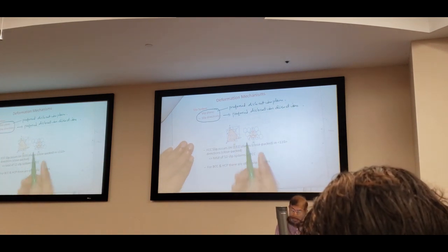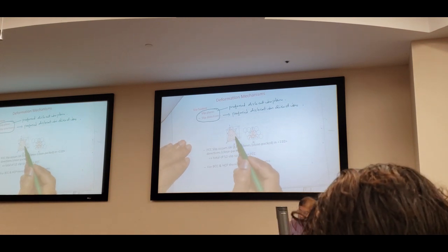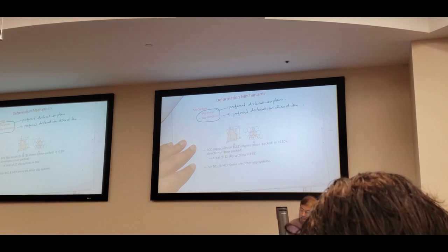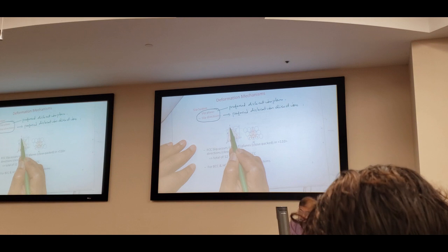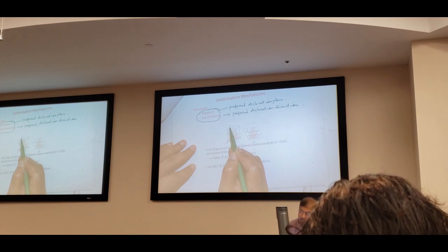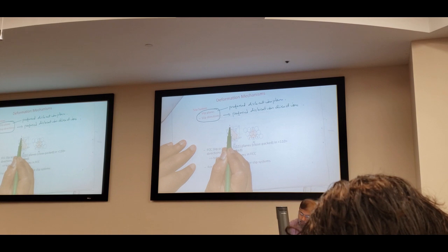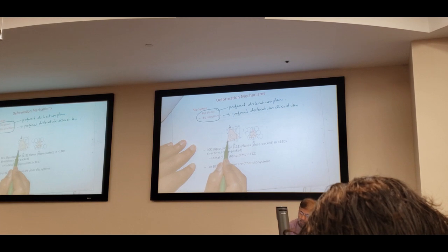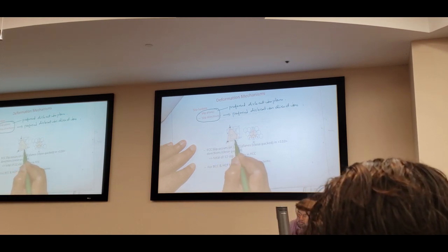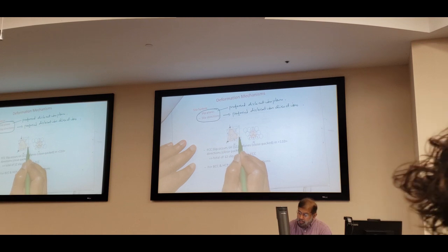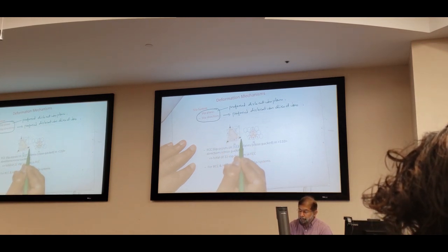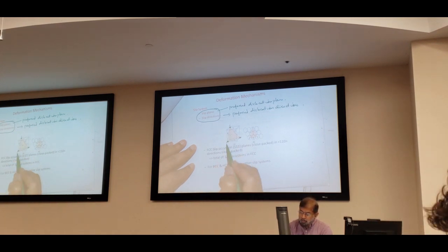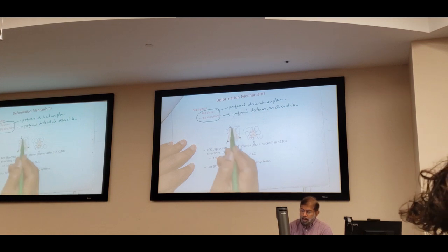Now look at this one. Here you have a face-centered cubic structure, FCC structure. And for our FCC structure, what is this one? The plane that goes from this atom here, along this direction to this atom on this side, and it goes along this one to the other side. And what is this plane? 111. This is a 111 plane. We use x-axis 1, y-axis 1, and z-axis 1.